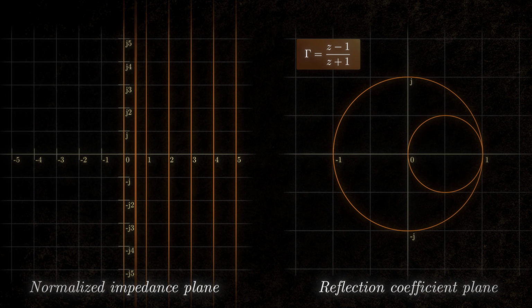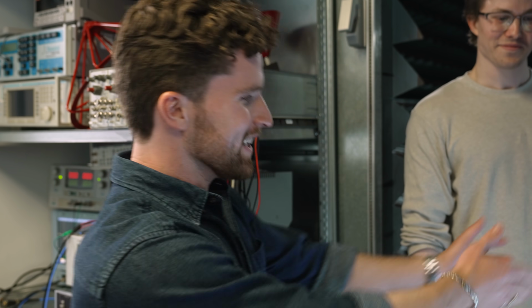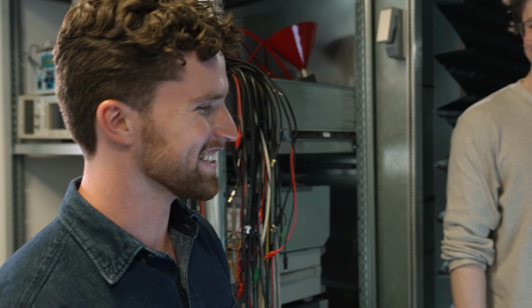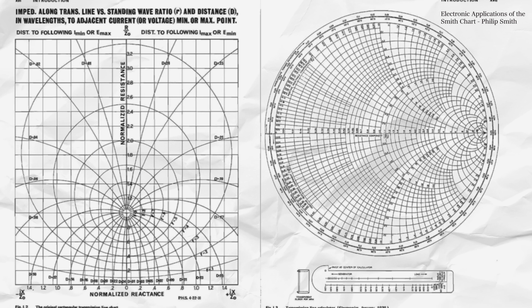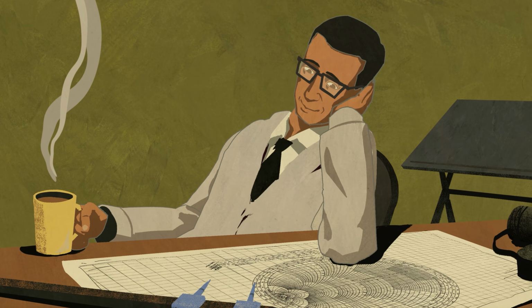I do think this is important. Like, we've verified that this crazy map switch from the complex plane to the reflection coefficient plane, leading to these insane appearing circles, they actually mean something. Like, in real life, we've used it to increase the power. Crazy. This is cool. This chart represented the whole problem graphically, and in a way radio engineers could actually use.